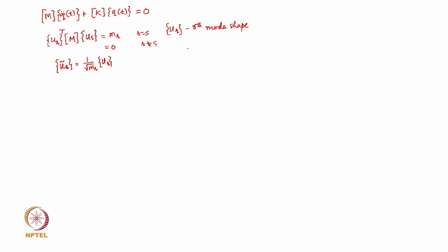You can get a mode shape like 1.05, 2.31 and 0.05. It is standard practice to normalize this with respect to the displacement of one of the degrees of freedom. So, I can keep this as 1 and then accordingly get the other numbers normalized with respect to this one, which makes more sense.